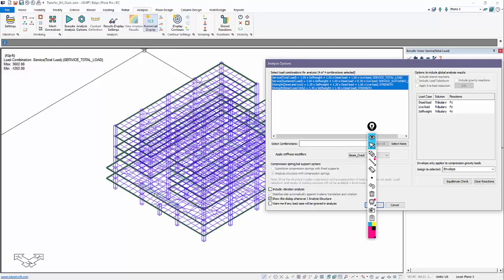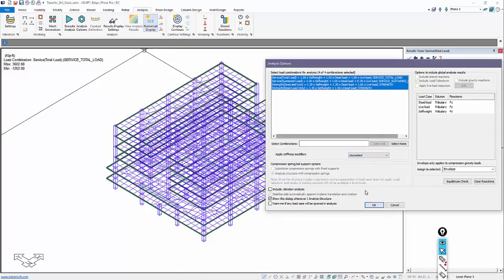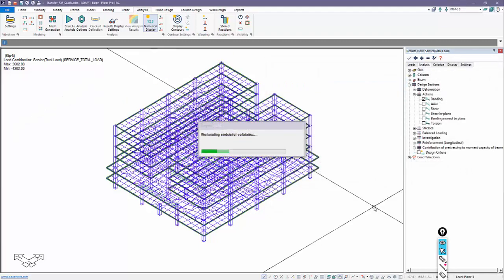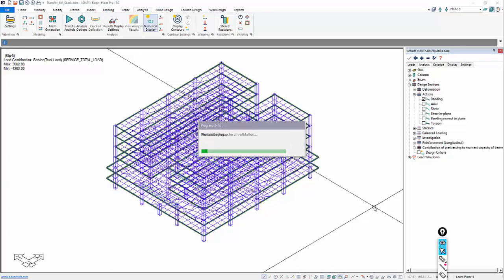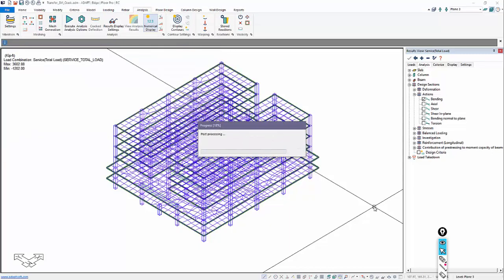So you crack those elements for the global solution. Okay, so that's fine. You could do that also. Now ultimately, if I'm running a full global solution, we're likely going to have other elements that are cracked to some level if we're applying modifiers. So here we're only cracking the beams for the sake of the example.